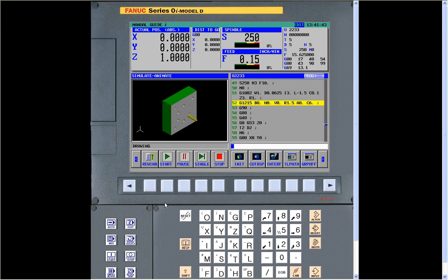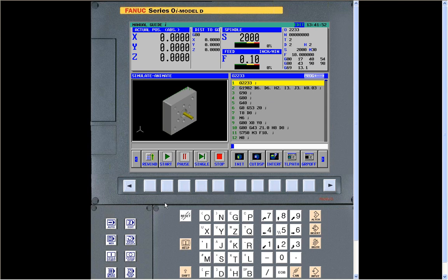Okay. There, it's tapping the holes. Now it's doing the pocket in the middle. Okay. And it does the outside. And there it's done. And then if we go right shift from there, we have a soft key that says insert. And it says machine time data is inserted. Okay. Yes. See, it puts the time.